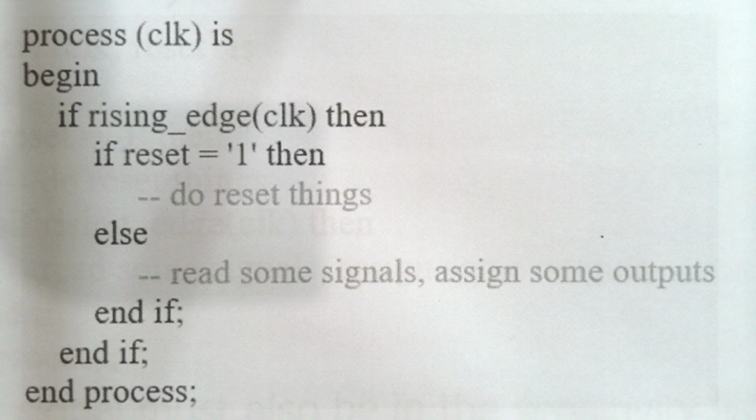Now the first thing to keep in mind is anything that your process needs to know changes of needs to be in a sensitivity list. Now that doesn't mean every single input port or signal needs to be placed in the sensitivity list. And we're going to learn what needs to be in the sensitivity list from these couple examples that I have coming. The first example is this register with synchronous reset.